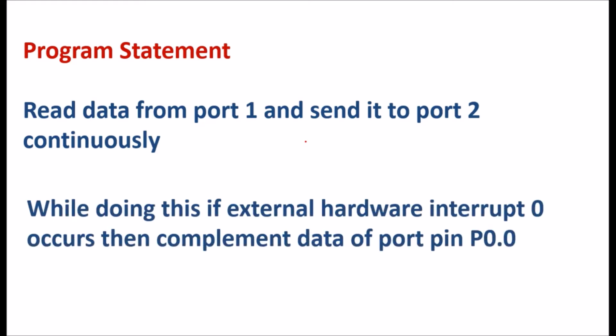While doing this, if external hardware interrupt 0 occurs, then complement the data of port pin P0.0. So whenever the hardware interrupt occurs, we complement the data at P0.0. If it is 0, it becomes 1. If it is 1, it becomes 0.